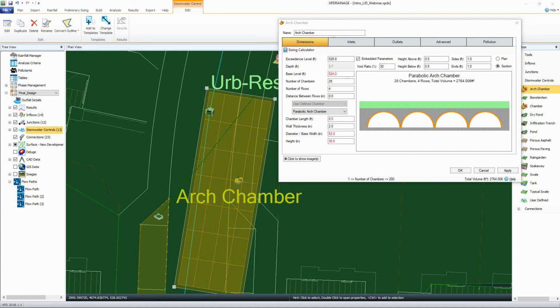you don't want to have a rain garden that will infiltrate on a steep slope because you might wash the road away. Again, that's a phone call you do not want to get. So you might have to wrap those facilities up. If you have an intermittent groundwater table, you have to worry about buoyancy, kind of a funny idea. But if you have a really high groundwater table and you wrap the base of a facility, you can buy soil, you buy media to do the filtration, but just wrap it up so it's not inundated from the in situ soil. That's one way to do it. But obviously you have to be creative, and have broader, flatter structures instead of deeper.